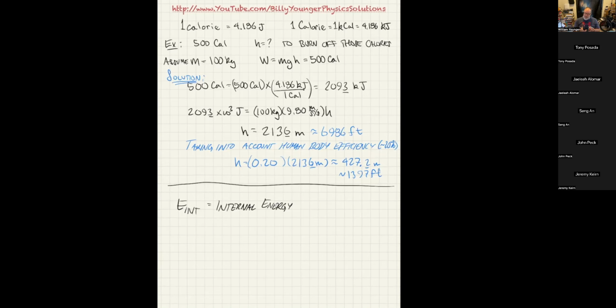That's because your body's not very good at detecting temperature. It's very good at detecting heat flowing in and out of your body. So when I'm doing this and I feel it feeling really cold, what I'm sensing is the fact that this tape measure is a pretty good conductor. So it feels really cold because it's taking my body heat, because specifically my body is at 98.6 and this is probably at 72. This too is probably at 72, but let's imagine this one being at 72 and this one being at 50.